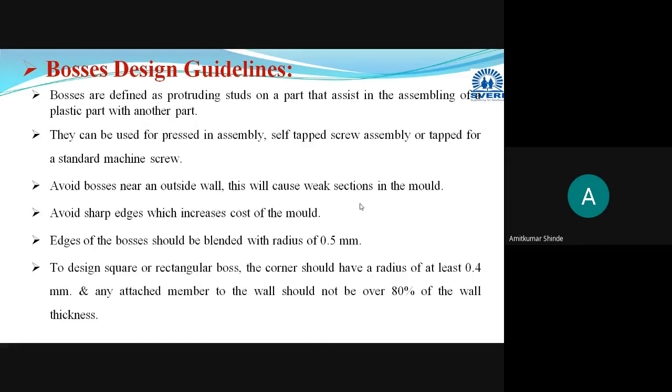Then avoid the sharp edges. Whenever sharp edges are there, more stress concentration will be there, and it will result in some cracks. Now whenever some edges are there in the boss, you have to give a radius of a minimum 0.5 mm.